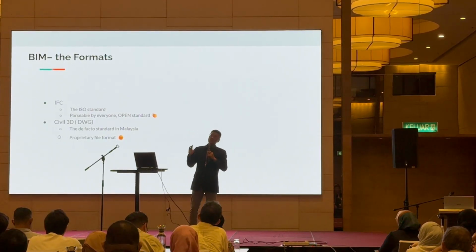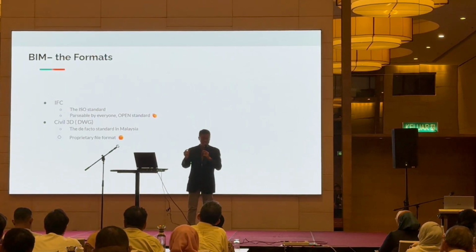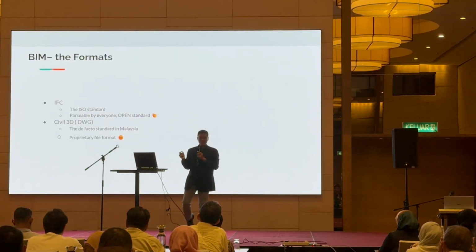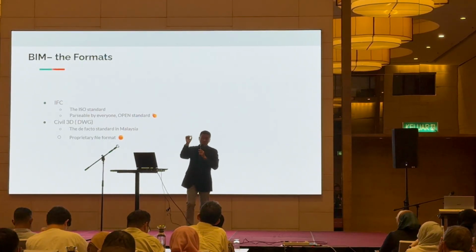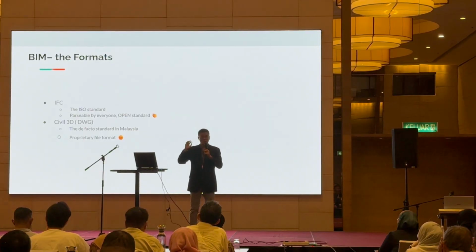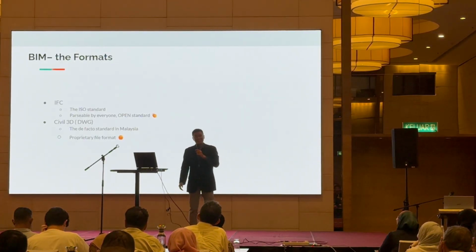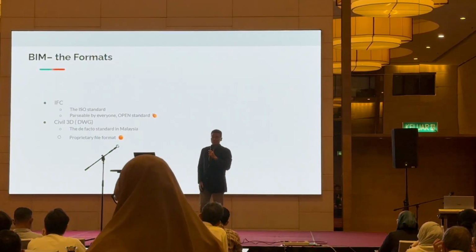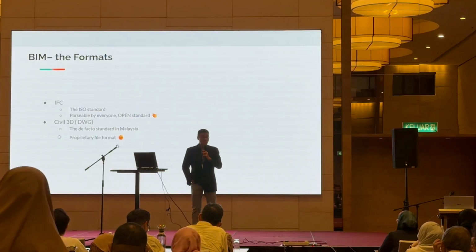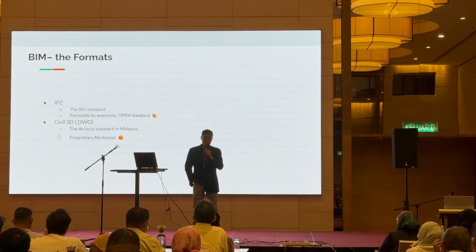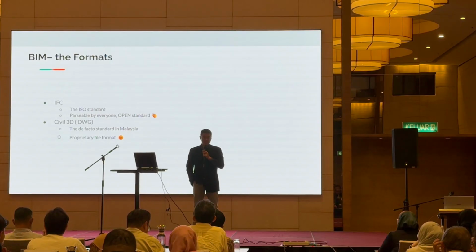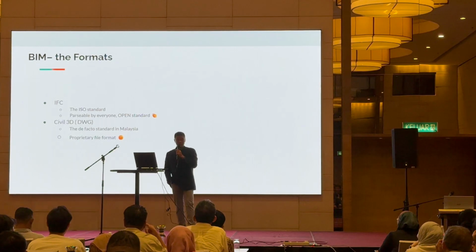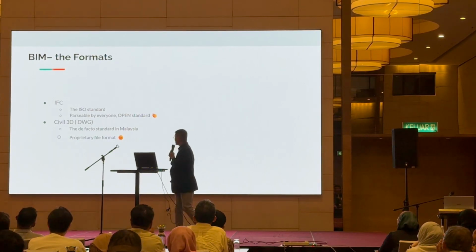When you right click and open an IFC file in Notepad, you can actually see exactly what is going on inside. I'm not too sure whether you have taken a dip into it or not. It's actually very fascinating. The IFC file itself is written in plain English. All right, so this is what makes it open. But by contrast, Civil 3D comes in the form of DWG format, which is not passable by anyone except Autodesk. You can try to open it in Notepad, but it will be all gibberish to you and to me because it is written in what we call binary format.